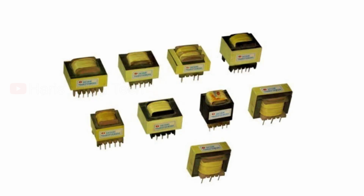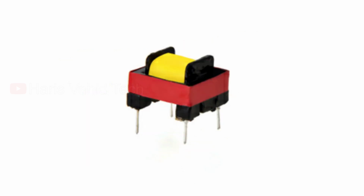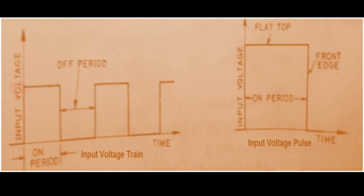The main functions of the pulse transformer are changing the amplitude of a voltage pulse, inverting the polarity of the pulse, coupling different stages of pulse amplifiers, and acting as an isolation transformer, etc. It should be noted here that the turns ratio of an isolation transformer is 1:1. The input voltage to a pulse transformer is of discontinuous type, as shown in this image.